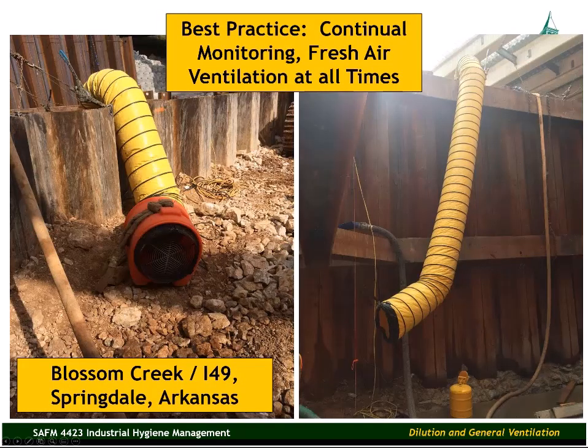The next slide here, we have a setup where we're using fans to blow fresh air into the space at all times. We're blowing that fresh air in. It's getting the air moving. We have a chimney effect in this space that's taking out the potentially contaminated air. We never had a personal monitor go off. We never got an alarm from any of the personal monitors that were being worn by workers in any of these sites. So our ventilation was working well.